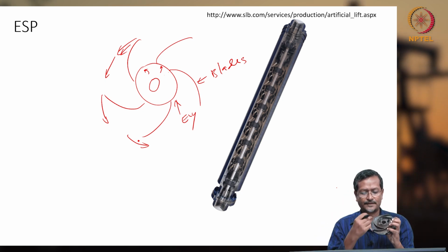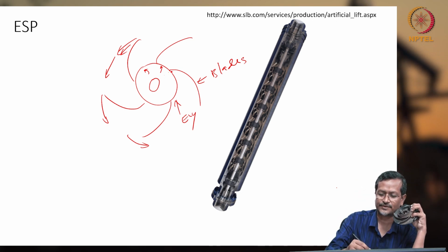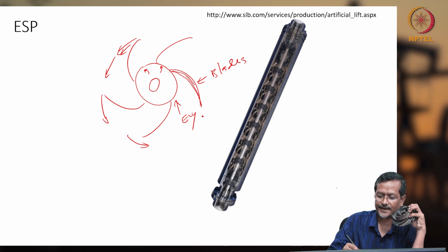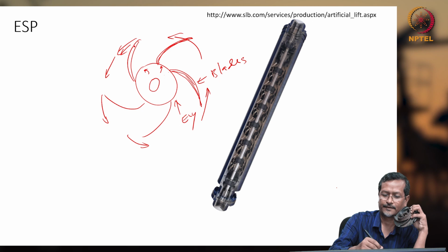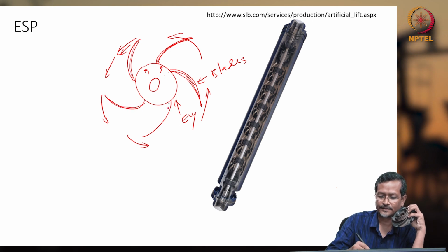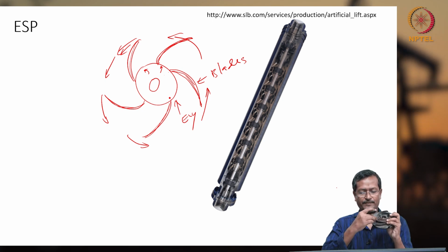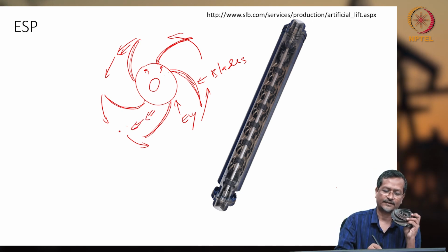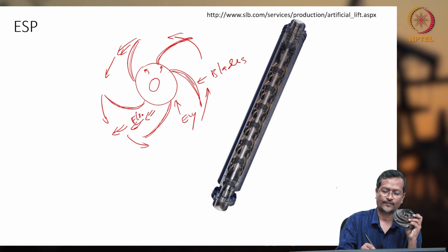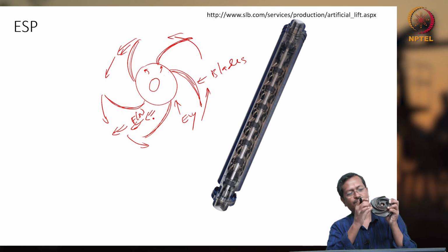When it is rotating, this blade will get one suction surface and one pressure surface. What is suction surface? What is pressure surface? So let's assume this is my blade, and the blade is rotating in this direction. Or vane, someone says. These are impeller blades. Because of the rotation, fluid will be passing through this channel, the fluid flow channel. So fluid will be moving like this,